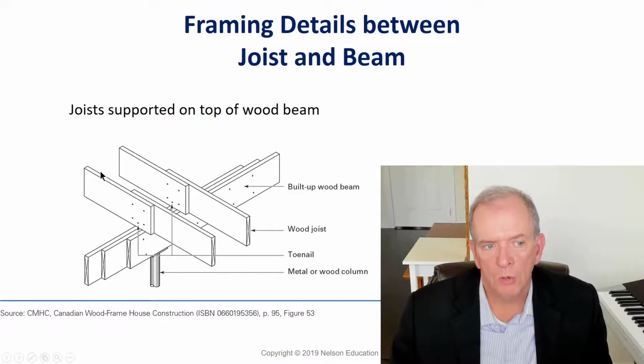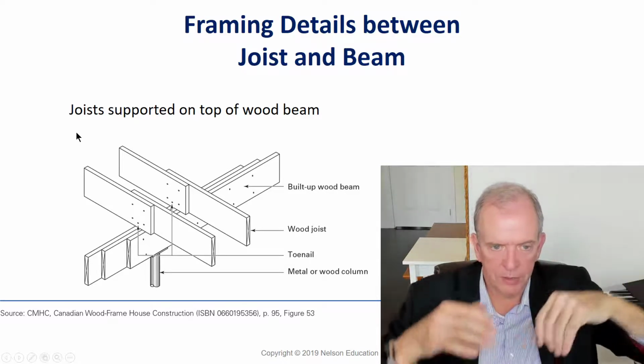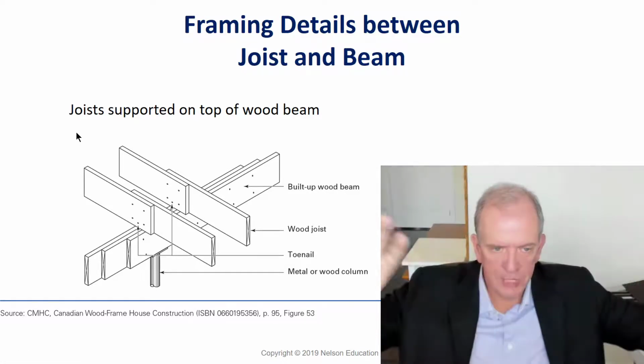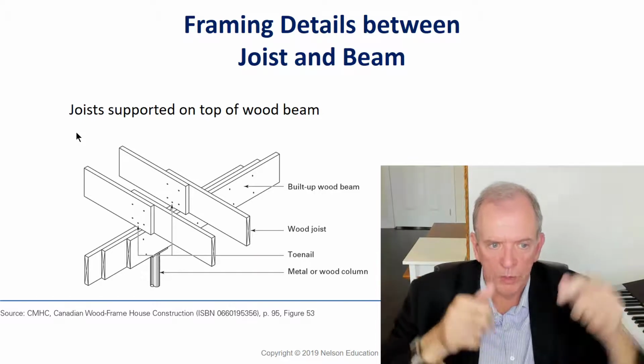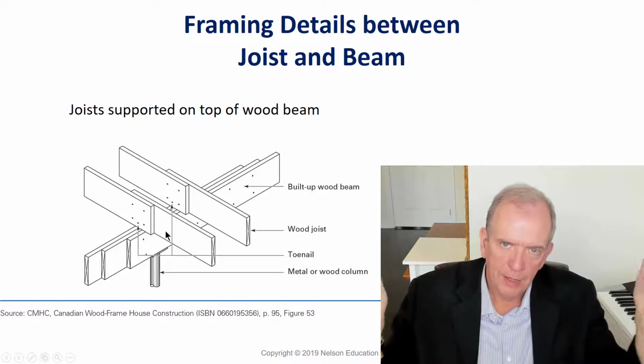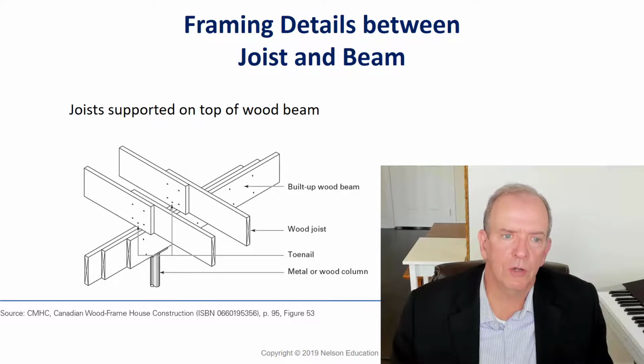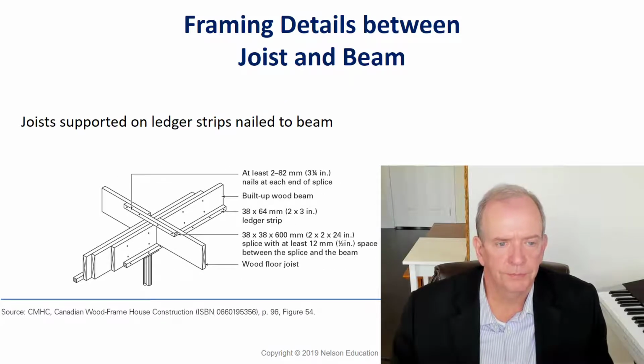It's way out here. Well, when this pushes down, remember there was that drawing we had where the beam goes down and it's under compression on the top and tension on the bottom. Well, when that goes down, what do you think happens to the outside edge if it's way out here? It actually goes up, and that would push up on your subfloor. Again, if you had a ceramic floor, that could cause cracking and problems.